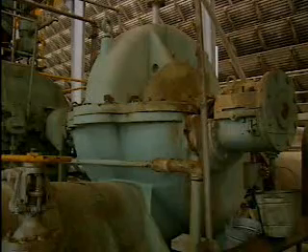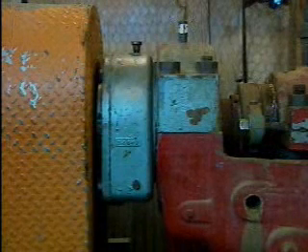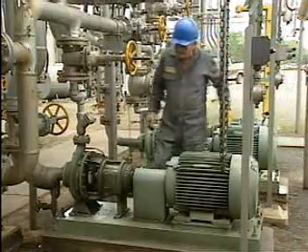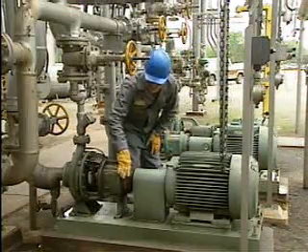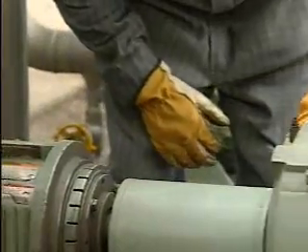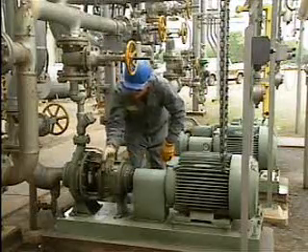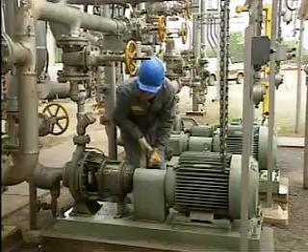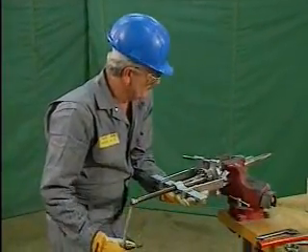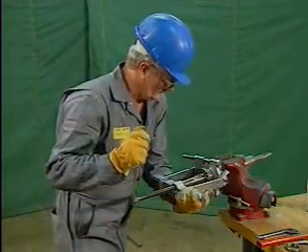Rolling contact bearings can last for years, but eventually all bearings fail. There are several factors that can cause bearings to fail and several specific types of bearing failures. Usually, it's possible to tell a bearing is failing before removing the bearing from the machine. Bearing failures are often accompanied by high levels of noise or vibration, high operating temperatures, and the smell of burnt oil. After a failed bearing has been removed and taken apart, other evidence of bearing failure may be seen.